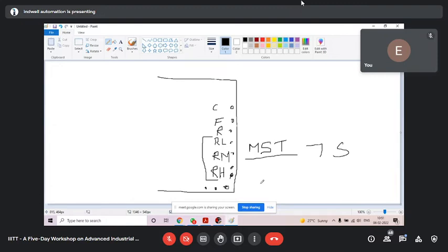All these terminals are for external control. Be very clear. One AC drive can control one motor without any external controller. So the AC drive itself is a controller to control all parameters of the motor. You don't need any external signal. But in industry, everything is controlled by PLC. So the PLC will only send signals to the AC drive to control the motor. That's why we have external control. That also you need to set.